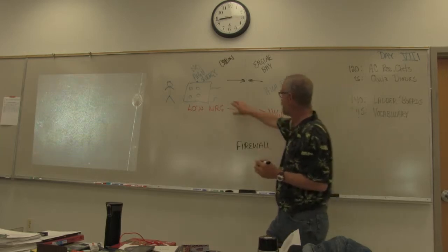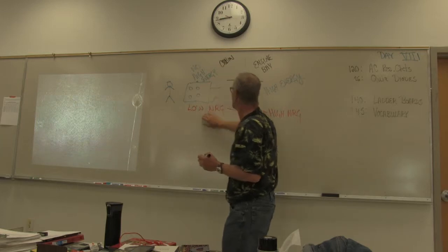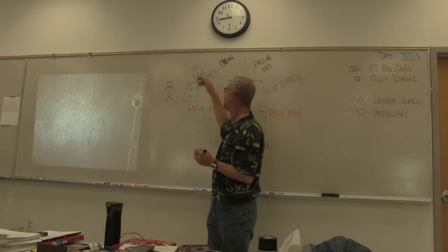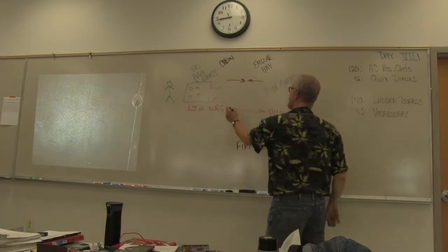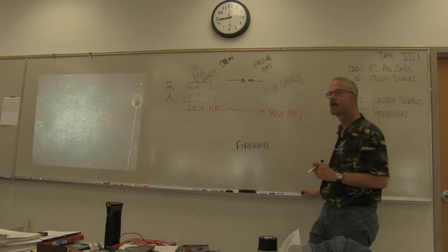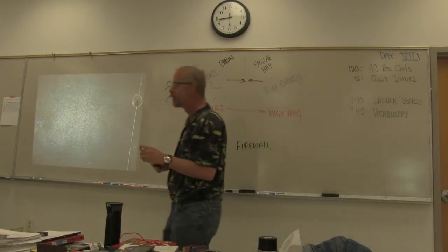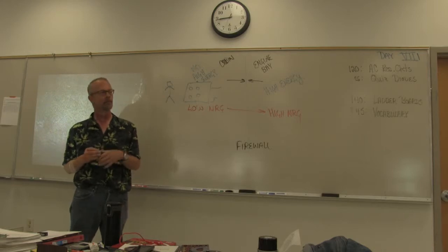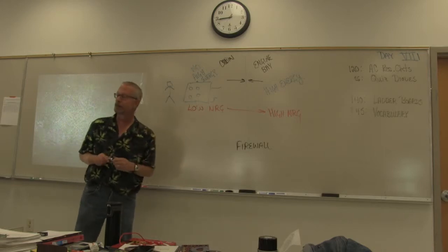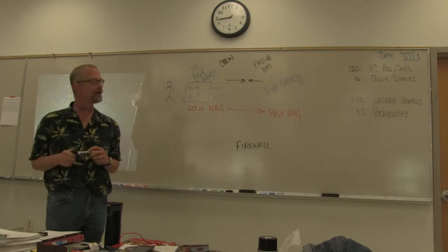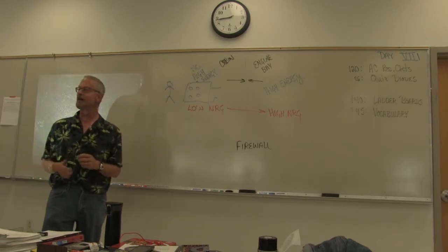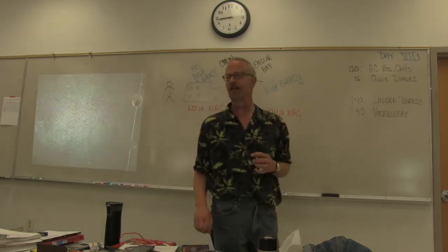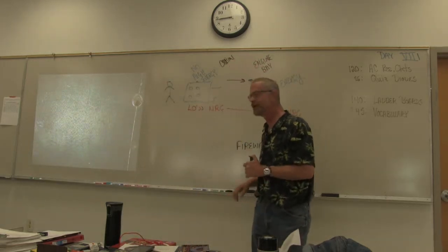Okay, so in some way we have to use low energy, which interfaces with a person, because low energy is more safe than high energy. And we need to use low energy to control that high energy. We do that in the car, for example, with the headlights, which run 10, 15 amperes sometimes, which is a lot of energy. We use what's called a headlight relay. When you turn the headlight button on, all you're doing is kicking another button, basically, that's in the engine bay and telling it to conduct the current required to turn the headlights on. Same thing with the starter relay.